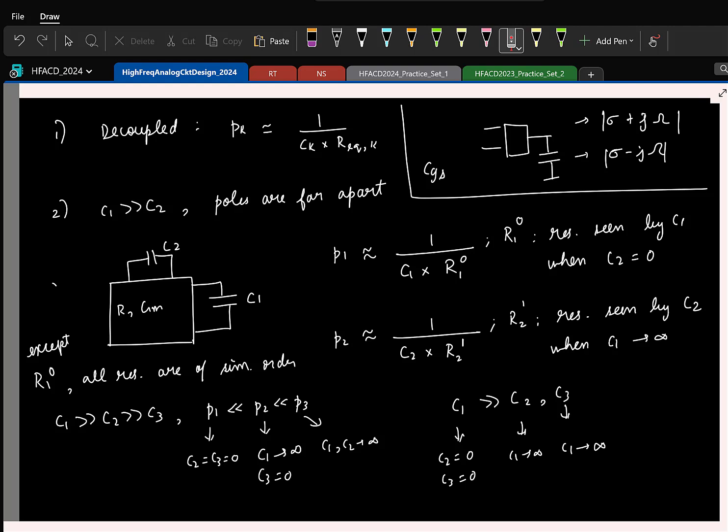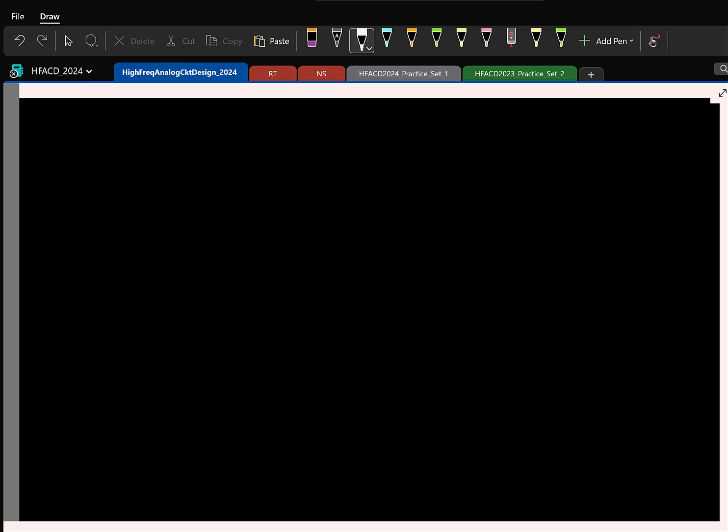Okay, so let's move on. A lot of time is spent. Let's look at a couple of examples maybe. The reason behind complex poles in the system is a different question. We'll encounter one such case, and we can see it at that time. Looking at the system, most of the poles we are interested in, the low frequency poles, will be real. If one pole is much smaller than the other, that has to be real. Because in real systems, poles occur in complex conjugate pairs. So if it is a complex conjugate, both should be at the same magnitude location.